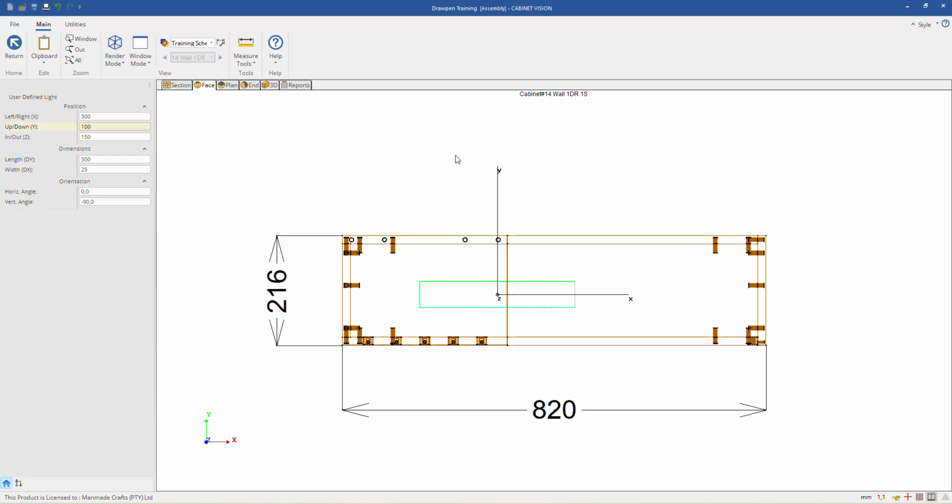There we go. Then you can move it a little bit more to the left or the right, using the left-right option just to get it nice and center. Can you put the value divided by 2? With these, I would rather advise to stay away from equations. It's just going to overcomplicate it. Just say plus 20. That moves it a bit more to the right. And then you can just add those little values until it looks correct.